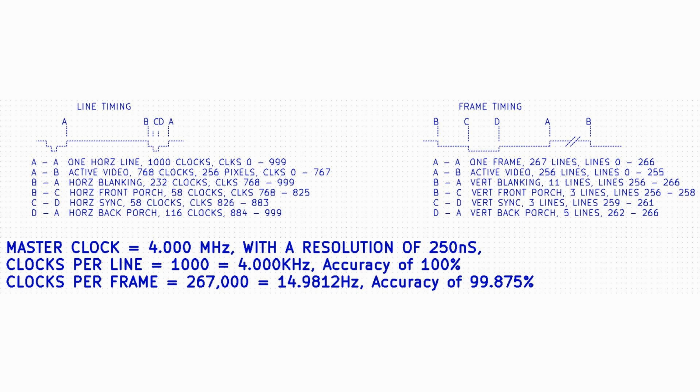The time from point C to D is a horizontal sync pulse. I show the horizontal sync and the horizontal blanking here superimposed in my diagram as a composite of the two so that you can see their relationship. Blanking starts and goes for 58 clock cycles, and then sync starts and it goes for 58 clock cycles, and then the back porch following sync lasts for 116 cycles. So that makes up the sync time. My diagram is not to scale per se, and so that from point B to point A would be approximately 25% of the cycle. It's a very wide blanking interval. Again, who cares? We will adjust the scanning size in the camera tube later so that the point from A to B, the active scan line, will scan across the tube at that point.